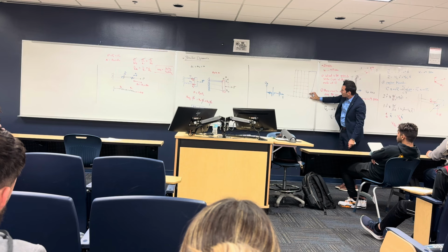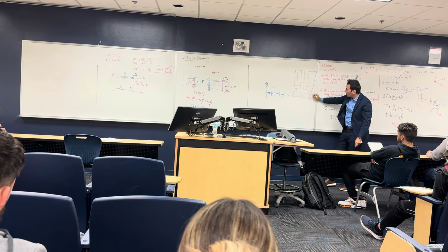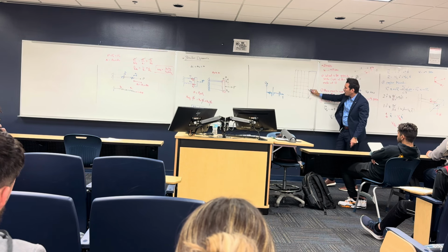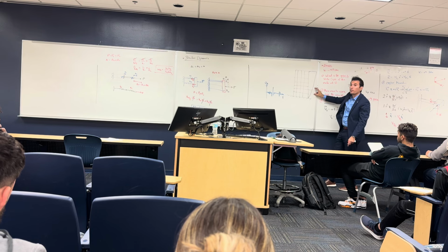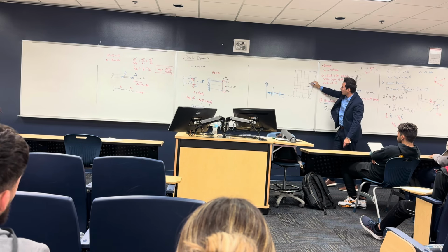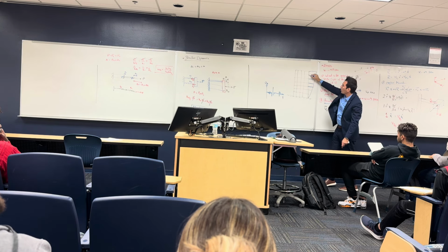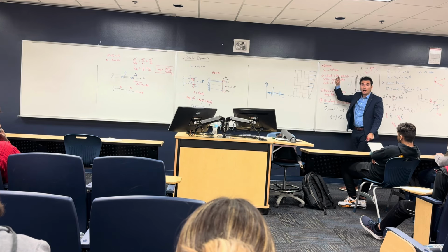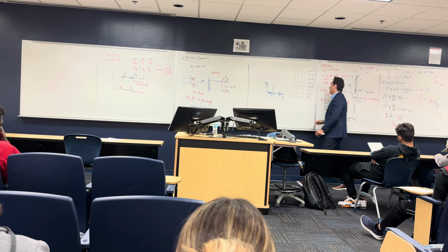Okay, so the slab on the top story is going to have a very high displacement. Why? Because it's going to add up. This one is going to move delta, and this one is going to move this delta plus another delta, and this one is going to move this delta plus another delta, so every one as you go up is going to have much higher displacement, okay?